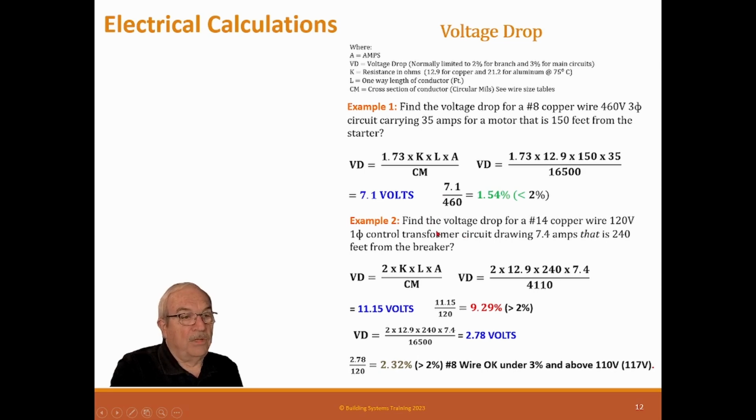Voltage drop, normally you won't be worrying about it unless you got something weird happening and you got low voltage. Now, what happens when you have a low voltage to a motor? It basically makes the amps go high, and you can burn a motor with low voltage. So voltage is important in a higher voltage, but even driving an actuator is a motor, and low voltage is kind of a problem.